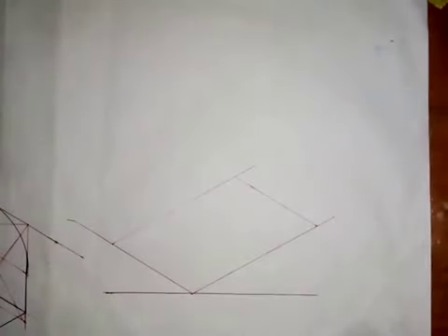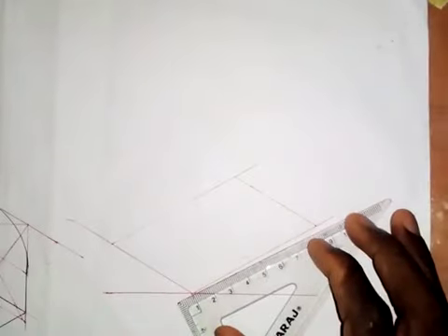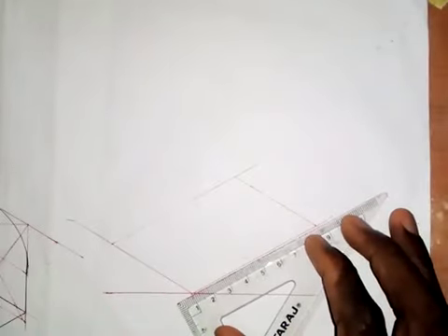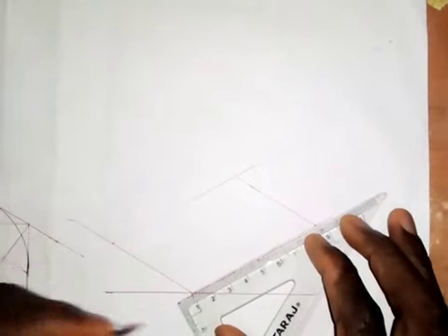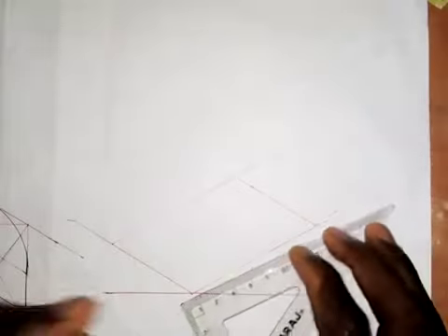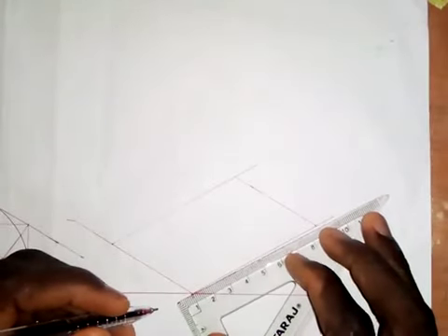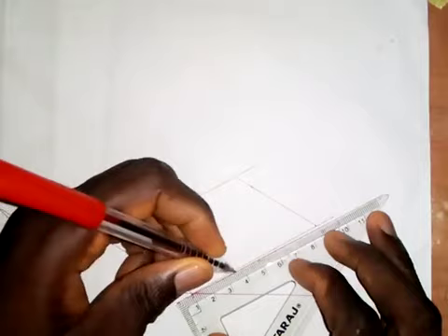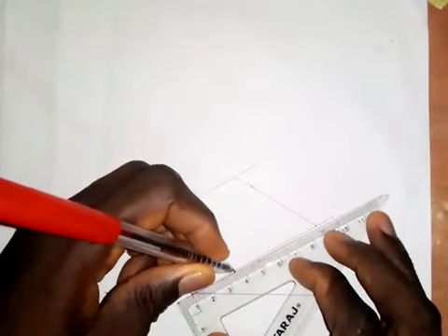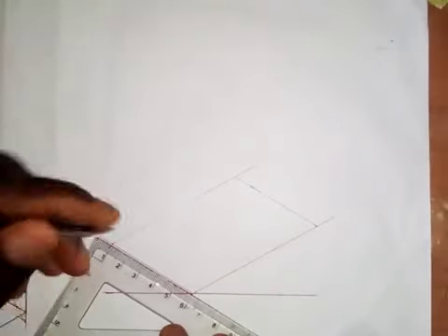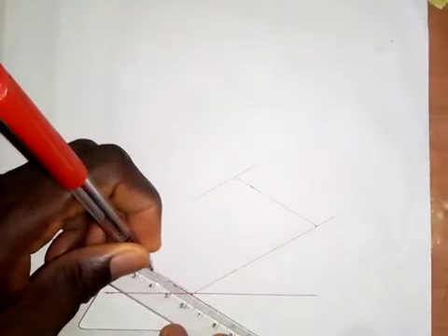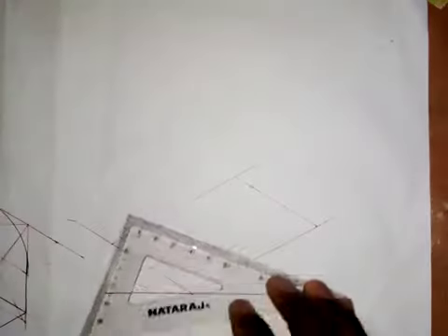So the next thing I'm going to do is to draw the curve, whose radius is 25 millimeters. So first of all, make this an isometric square of length 50 millimeters. Okay, so I need to get 25 here. The midpoint is 25, and also I need to come here and get 25 millimeters. So this is 25 millimeters.